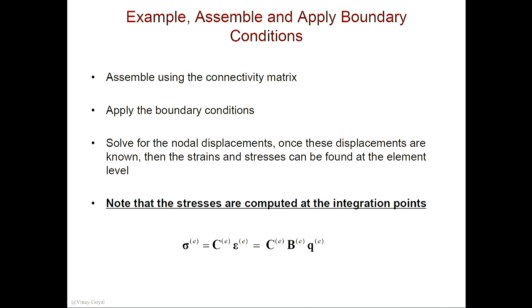These stresses are typically calculated at the integration points, Gauss integration points. That's how you calculate this. Because remember, B bold depends on xi and eta, or R and S. And so for that reason, you evaluate these at the Gaussian points. And so if you went to Abaqus and queried an element, the values of the stresses for an element, if it's 4 integration points, it's going to give you 4 values. And those 4 values represent the values at the integration points. Okay?